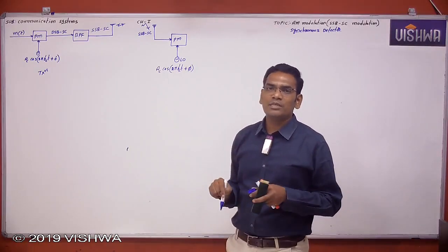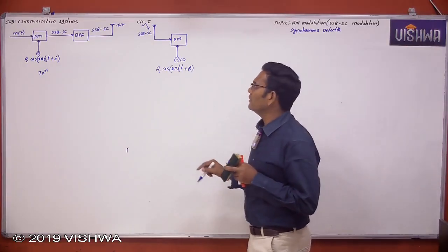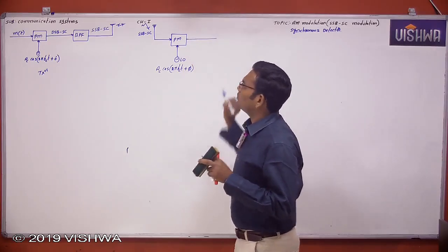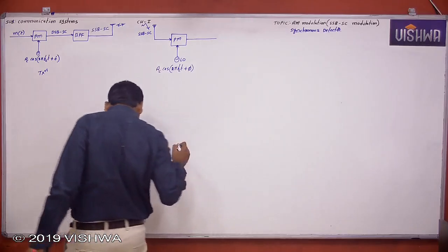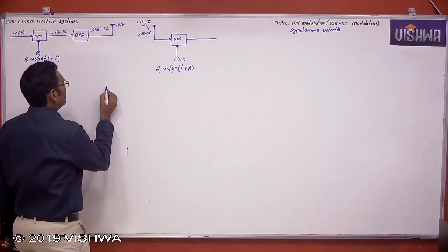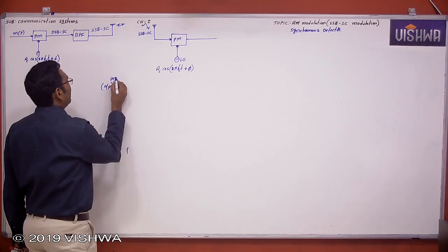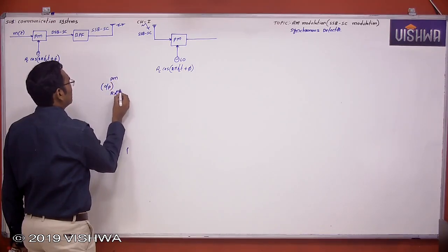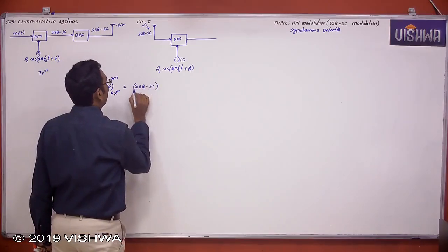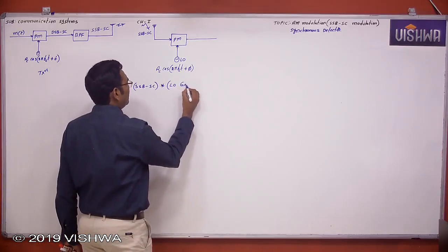What happens with the phase mismatch? We already covered it in AM and DSB-SC, but now we will see it in SSB-SC also. So what is the output of the product modulator at the receiver? It is the SSB-SC signal multiplied with the local oscillator generated signal.